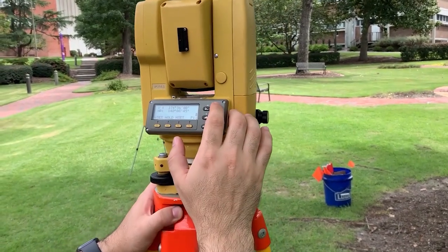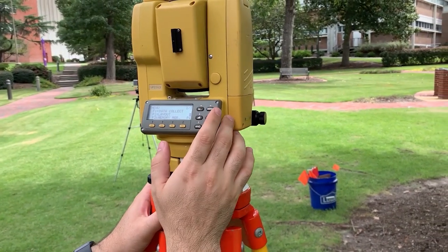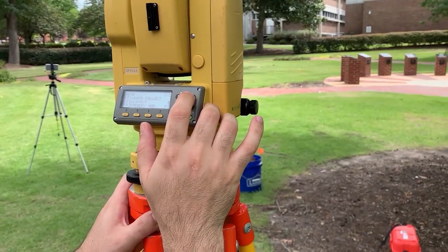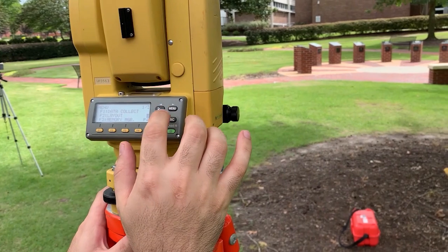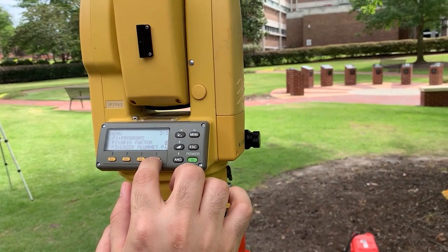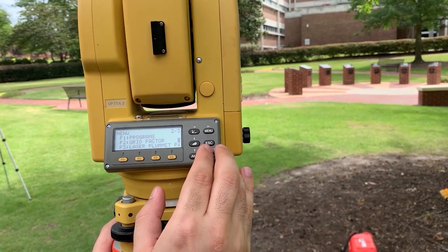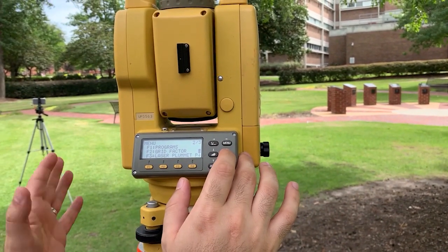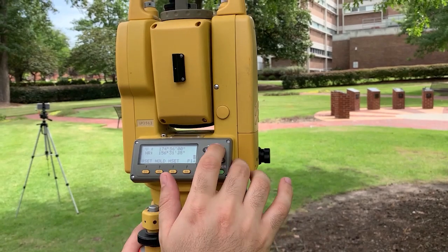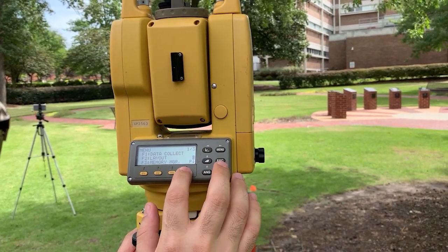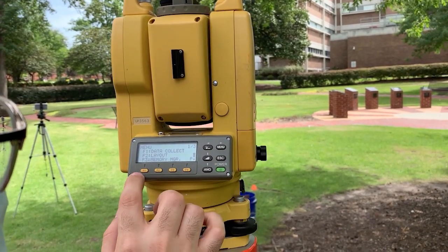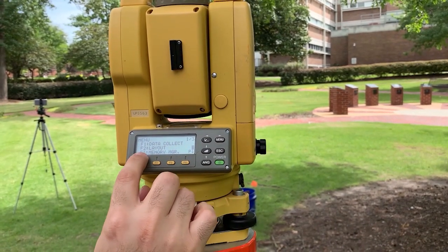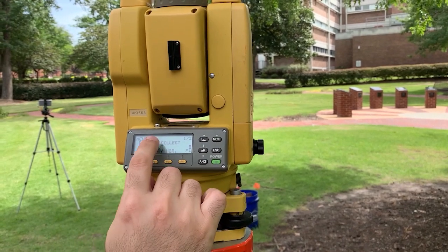When you turn it on, you need to make sure it is level. And if it is not level, it wouldn't let you use it. So each total station would be different, but basically what you need to do, go to menu, and then you see it has 4 keys: F1, F2, F3, F4, and it shows here which key would do some functions.